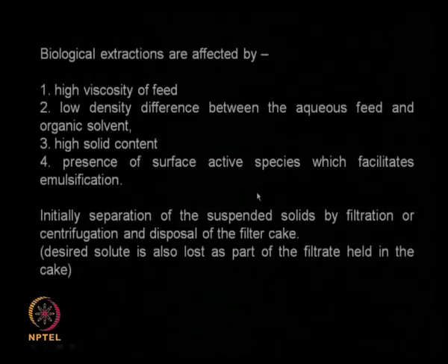One could be your solvent and one could be your original broth, and then there could be some layer which may contain a large amount of precipitated solid. There could be another layer which may have a froth or foam created because of the presence of the surface active species.